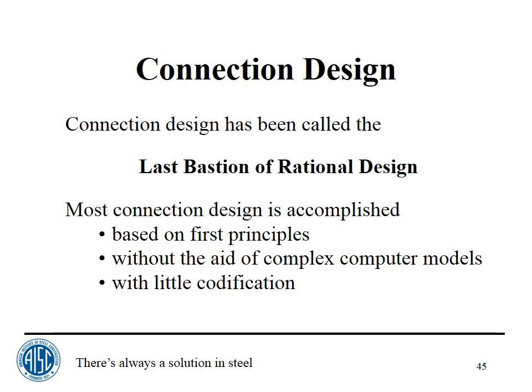But connection design, I'm not talking about the stuff you can look up in a table, but I'm talking about that lead-in slide that I showed you that showed really complex connections. You can't find anybody's software to do that for you. So connection design is based on first principles, without the aid of complex computer models, and with little codification. The codification that exists, we've already talked about. I mean, it's sort of the limit states for all the different parts, but there's no specific codification about what particular set of internal forces you should use for these connections.